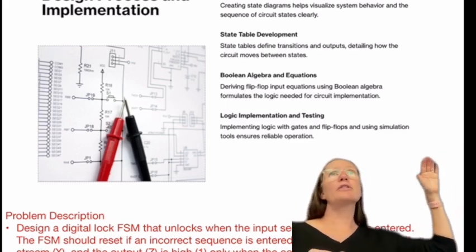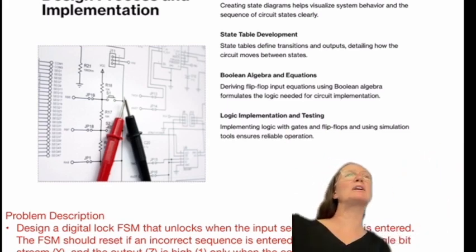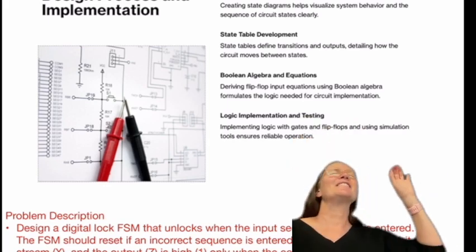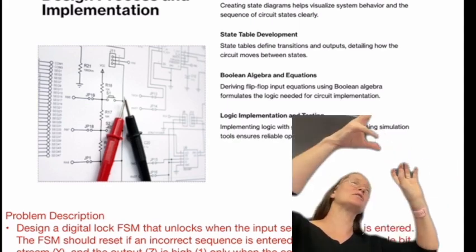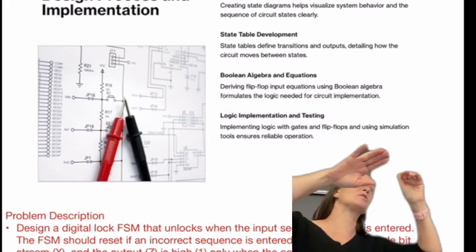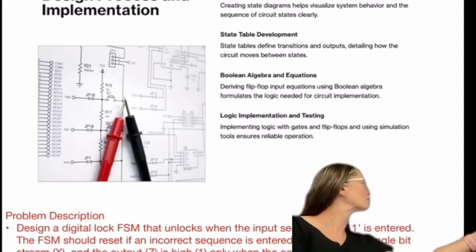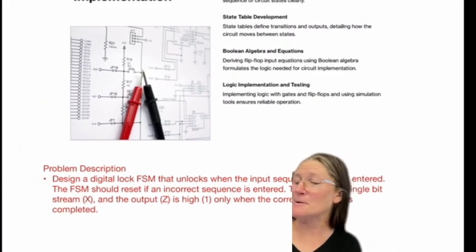With that flip-flop you have the input, which is the old state, and the output is the new state. Your next state comes from the digital logic, and that goes into the flip-flop. Once the clock goes, it changes the output of that latch. Anyway, it'll be easier to see it visually, I think.